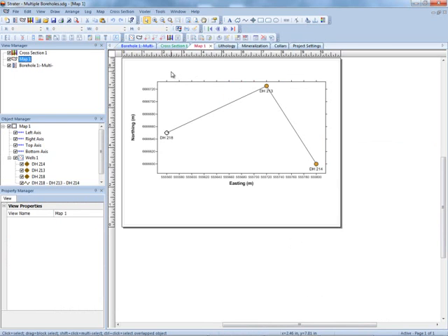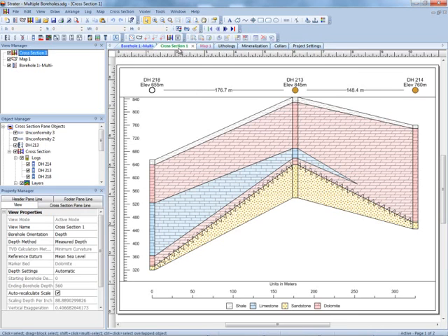If you create a well map, you can connect specific wells with a line and use it to generate a cross-section. The Cross-Section View tab is green. Cross-section views show cross-sections based on interval data, such as lithology data, like this example, or depth data, such as geophysical data. The wells are automatically connected with layers when using interval data.